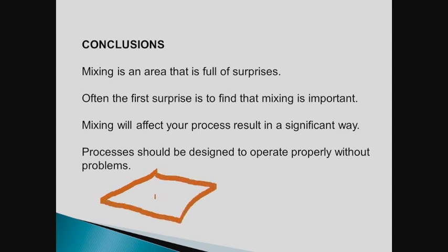the capillary suction test. You get a test tube and invert it on blotting paper. So you have your filtrate in here, and basically you'll build up a filter cake right in there. And you'll have timelines in here as the filtrate goes through the cake and into the blotting paper. This essentially gives you a measure of cake resistance. That would be called the capillary suction test for filtration.